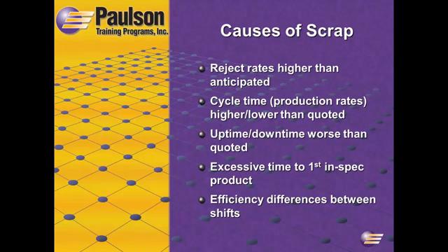These things are inevitable. Cycle time or line speeds for your extrusion guys is another biggie. No offense to anyone out there, but what's the harm for the shift manager on third shift to say, you know what, life's a lot easier when I increase the cooling time by a second and a half a cycle, the parts come out better. Well, it's not what we quoted, so there is some harm to it perhaps, and I'll show you a little bit more. We have a spreadsheet analysis that we offer on our website that goes into detail on the harm and the cost of things like that.